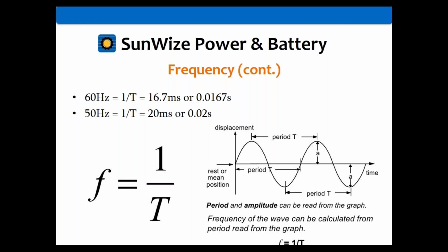And that's important because a lot of inverters now have transfer switches built into them. You've got inverter chargers, and other inverters have transfer switches in them. Those transfer switches have a time delay. Some could be as fast as 6 or 7 milliseconds and take as long as 50 milliseconds.